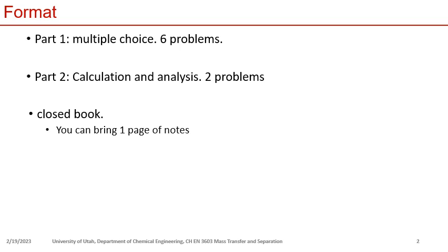So that's the equimolar counter-diffusion problem. And then we also discussed the Baker problem, which is also called unimolecular diffusion. In the two bulbs problem, component A diffused to the right, component B diffused to the left. So you have both species diffusing at steady state. But for the Baker problem, it's slightly different. You have species A, which is a liquid evaporating and entering the air. Meanwhile, you have species B, typically air, diffusing down and trying to dissolve in species A and making a mixture.